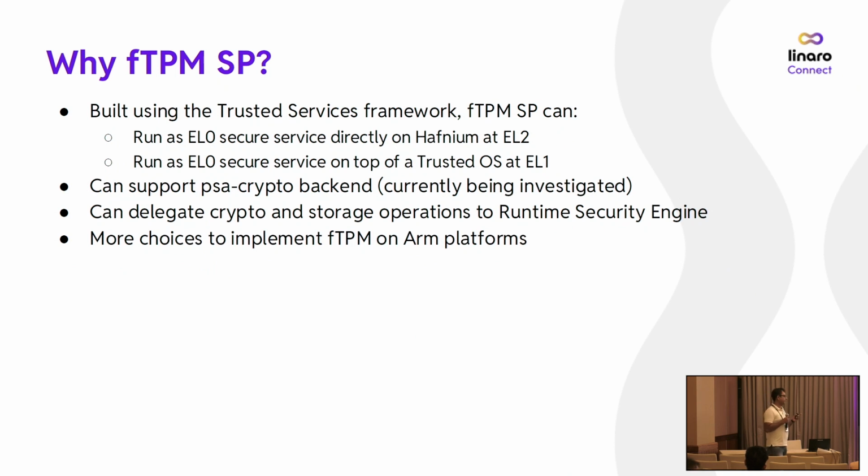If we're able to integrate the PSA crypto backend into fTPM SP, then we are also looking into delegating both PSA crypto and PSA storage operations to the runtime security engine for improved security. And last but not the least, having more choices to implement fTPM on ARM platforms is always good. Partners can choose the right solution based on the requirements and the platform capabilities.